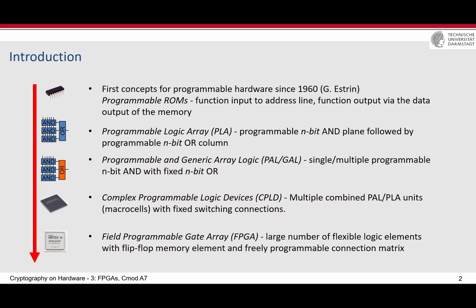And then afterwards, it was supposed that this is too complicated, and many configurations, so they did something else, which is called programmable array logic and generic array logic, which is called PAL or GAL. And it means that the AND part is configurable, but not the OR part. The OR part is completely fixed. We will see that.